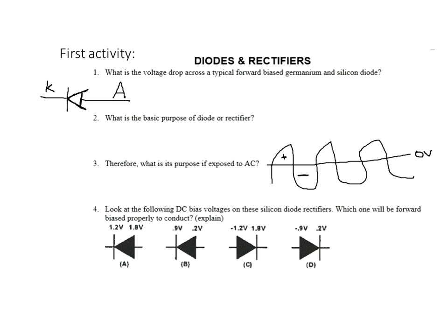Well, if I expose it to AC, the AC becomes rectified, and depending on the direction of the diode, it will either keep one polarity or the other. So the duty of the diode when exposed to AC is to keep one of the polarities and eliminate the other. So if the diode was pointing to the right, these would stay and these would go away. That's what would come out. If you turn the diode over, these would stay and these ones would go away.